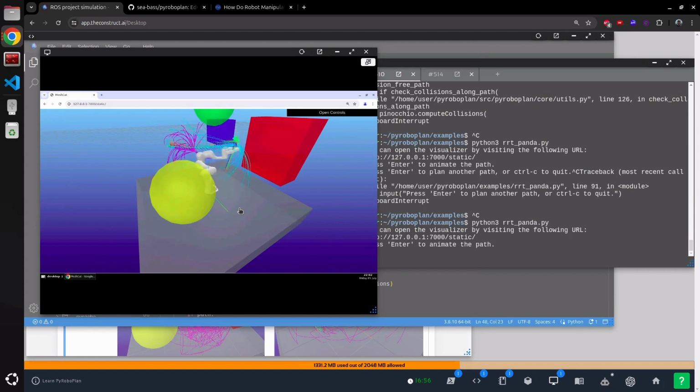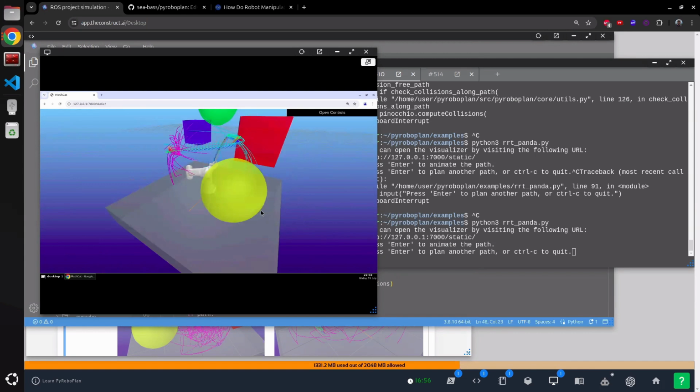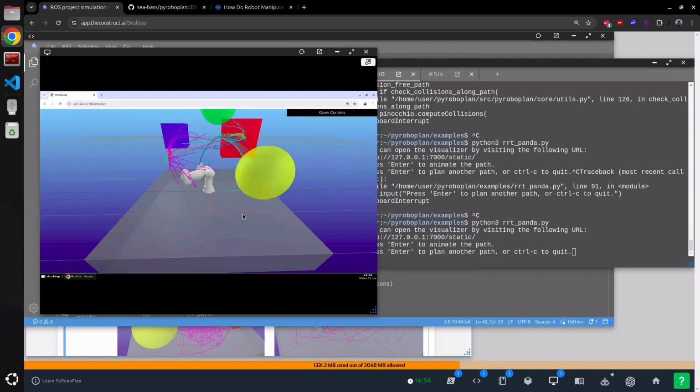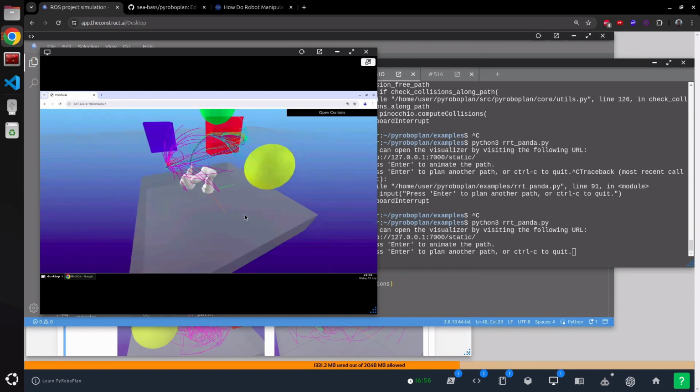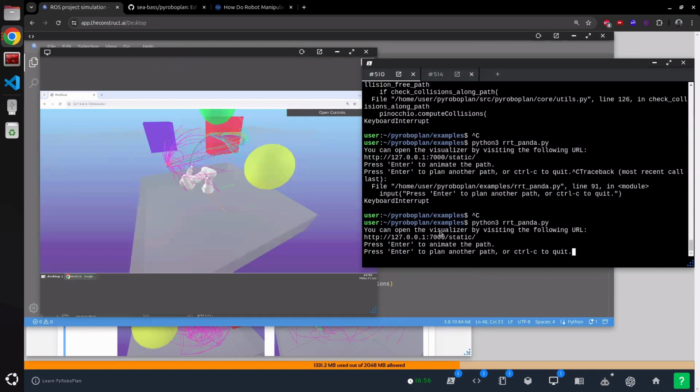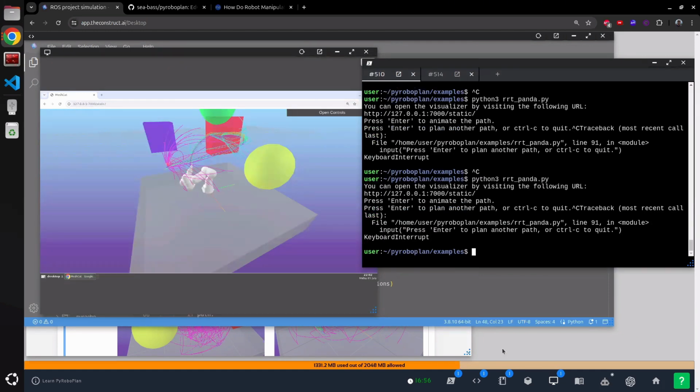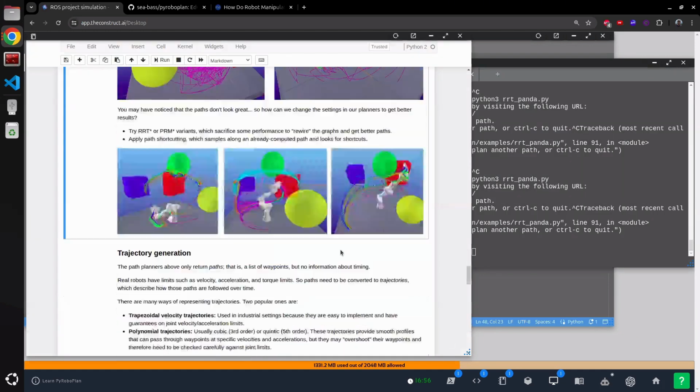Yeah. So hopefully you can play around with that. There's lots of other types of motion planning, so we're not going to stop there, because there's a couple of things that we need to talk about still. So we have these paths, right? In all these animations, I'm just basically picking a constant velocity for the robot to follow the path in. But we know that that's not necessarily feasible because your robot might actually have limits associated with them, like we talked about things like maximum velocities or maximum accelerations. So that's where you get into the area of trajectory generation.